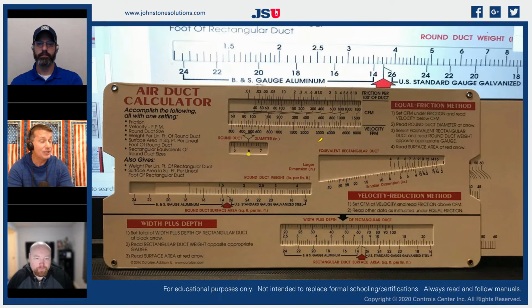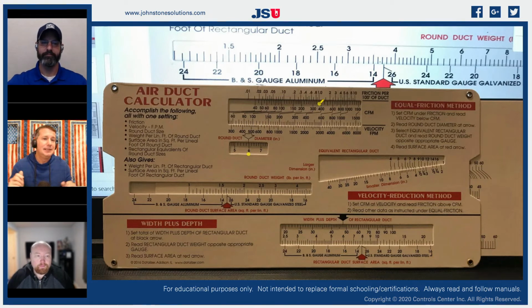Well, if I had actually designed my ductwork and I had a blower capable of doing it, and I had a true inch of static on that particular duct, I can squeeze a lot of air through that thing. I could actually squeeze at 1 inch 380 CFM through that same 6-inch round. That's a lot of airflow. That's almost 4 times the airflow that I have designed it at. So here's the consequence. What happens when I put an inch of static on a duct?